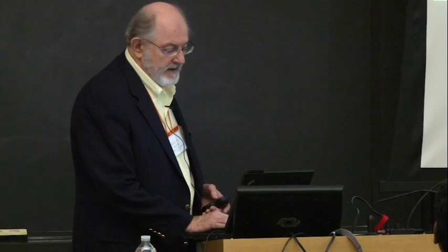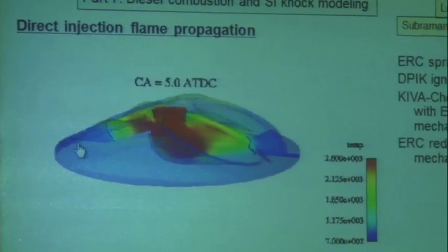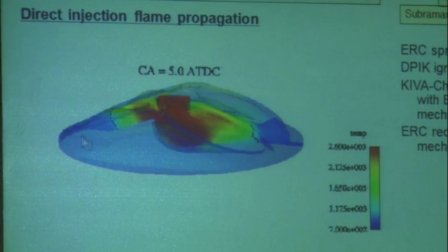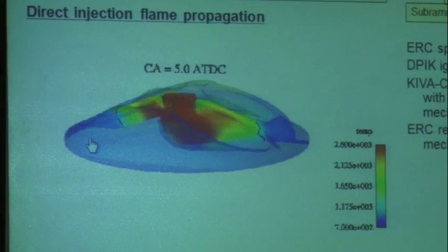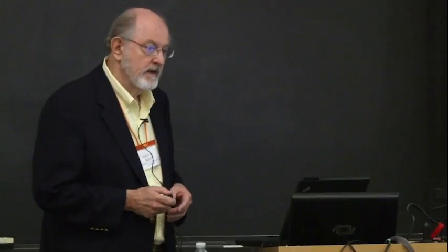So the question is these hydrocarbons, and all I'm saying is that because of this combustion chamber geometry, it's very difficult for this flame to propagate all the way to the edges of the combustion chamber. You see how it's narrowing down in this triangular pent roof configuration. So at a certain moment, your heat losses to the walls and the piston are so large that you stop combustion. So this is more applicable to this particular design.